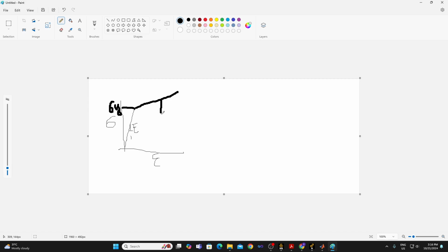One is that once you unload, it follows the initial slope, that is the slope of the elastic region, and that way the range of the elastic region increases. So once it unloads, it goes over here, follows this line, and once it reloads, it still follows this line. When you yield it for the second time, the yield stress now increases, and that increment is called the hardening stress. Let's denote it with x.